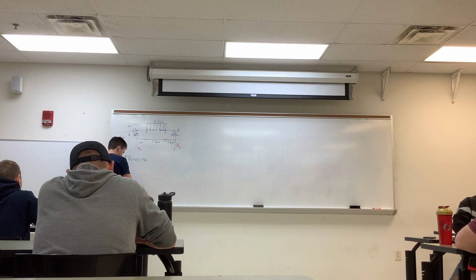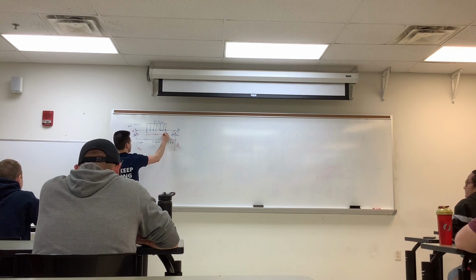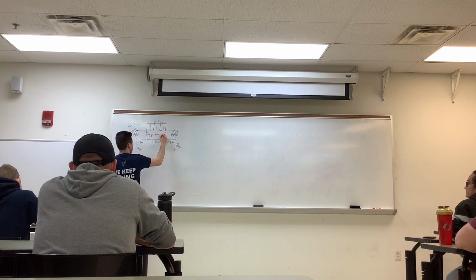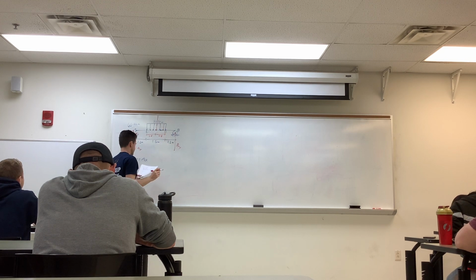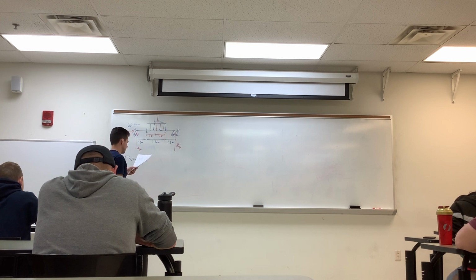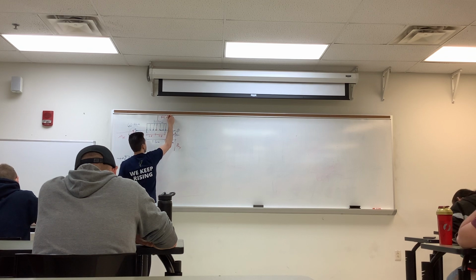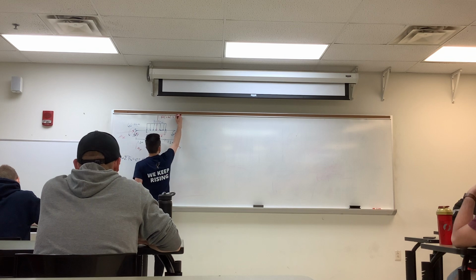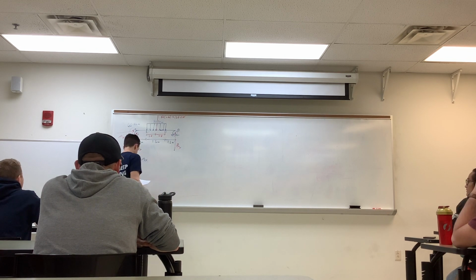We can convert this distributed load into a single concentrated force. Splitting this up, we have 0.8 meters and then 0.8 meters. Then converting this into a single force, all we do is multiply that 80 kilonewtons by the distance it's over, so 1.6, and we get that to be 128 kilonewtons.